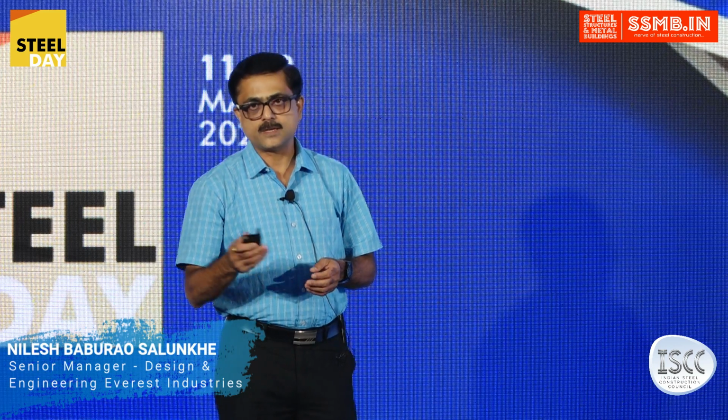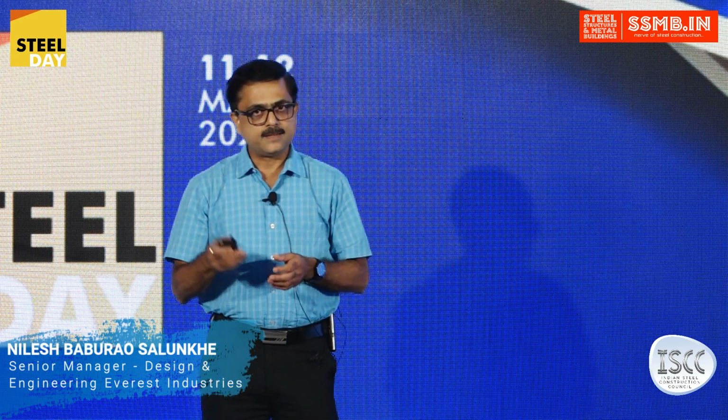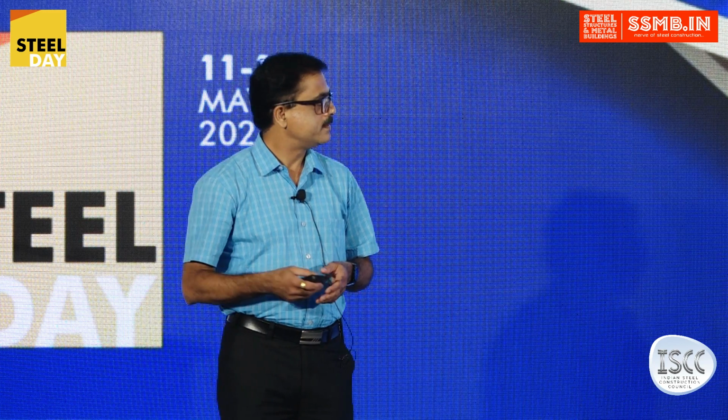So the second question we should ask is: are those the only factors that affect the strength of the section? Does any other factor affect the strength that is not accounted for while designing the sections? Currently, while reviewing the IS code, the design strength of the beam is generally given by the equation beta B, Zp, and Fbd. This is the generic equation, and the code applies some reductions in order to take care of those initial imperfections, the load applications, and the factors I have discussed before.